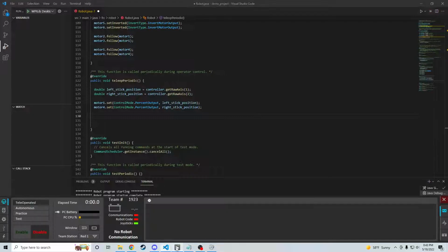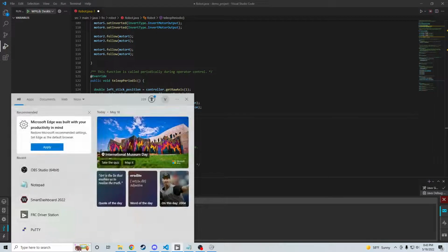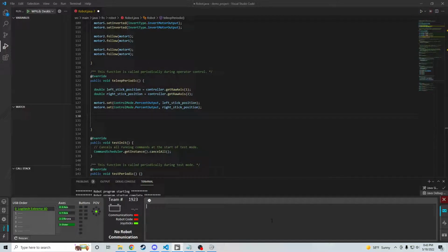So why don't we go to driver station and look at the buttons that are in the controller. I'm pressing the trigger on the controller. That's the first button slot. On controllers, the buttons start at 0, just like axes and ports for the actual controllers. That first button square goes down vertically. The list is, this is 0, this is 1, this is 2, and so on down to 10, 11, 12. So we're going to look at button 0, right?